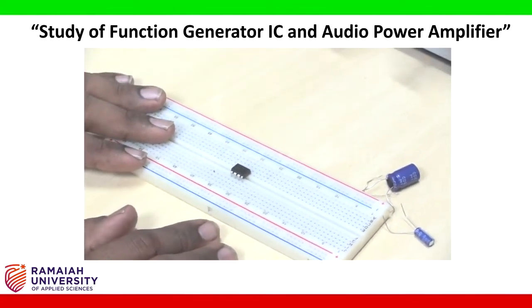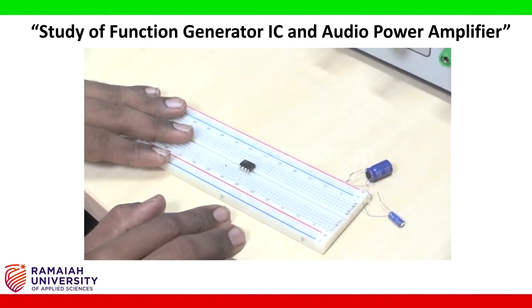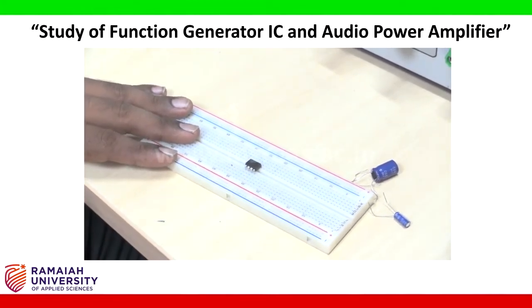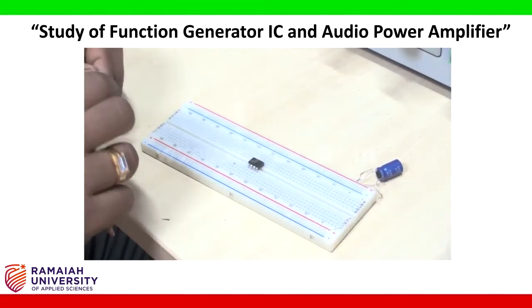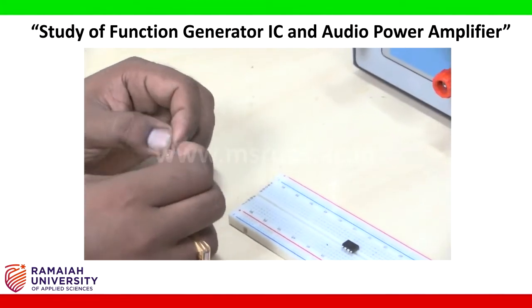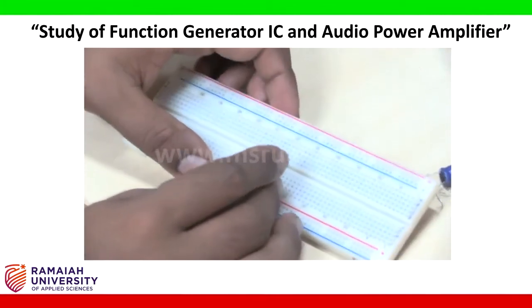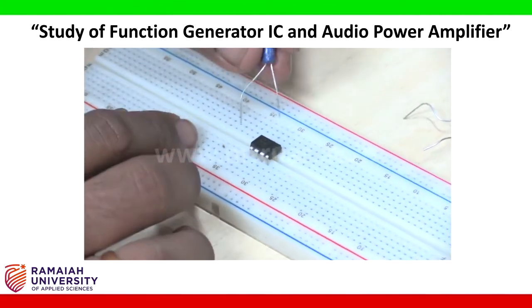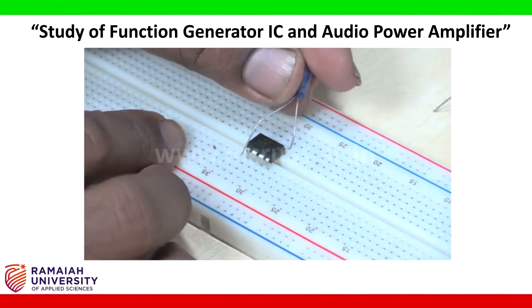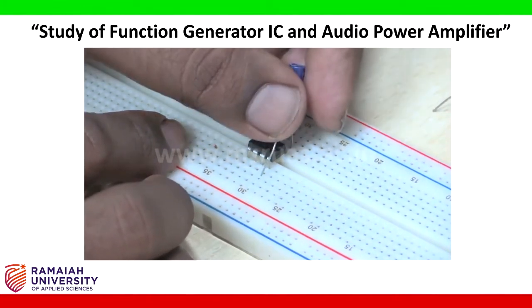Now I am going to connect pin number 8 and pin number 1 with a 10 microfarad capacitor. So this is the 10 microfarad. I am taking the 10 microfarad and connecting pin number 1 and pin number 8. So this is pin number 1 and this is pin number 8.